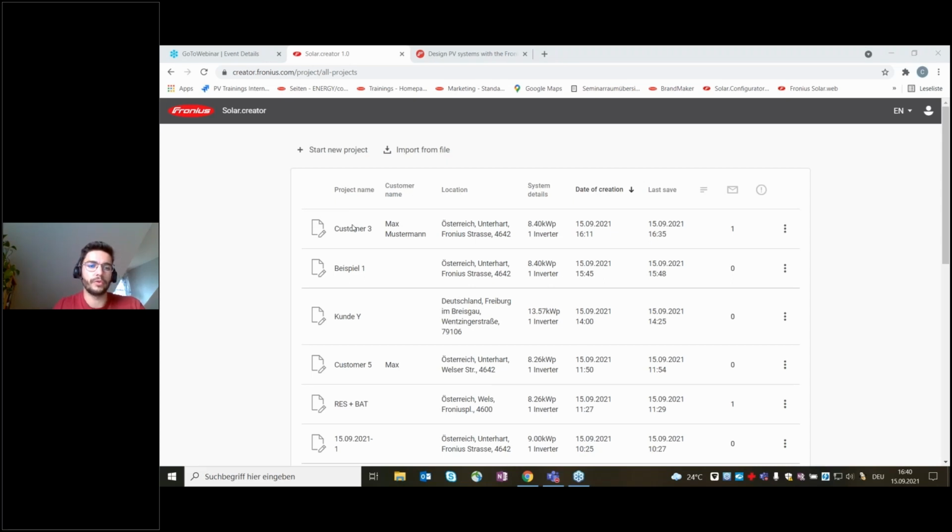So there is one really good question, for example, if we exceed the inverter capacity, so if it's the voltage or the current, will it still show you a result? So this is really a good thing, and this is one thing which our tool does. So if you exceed the limits, doesn't matter if it's the current or the voltage on the PV generator, it automatically won't show you the systems above that.